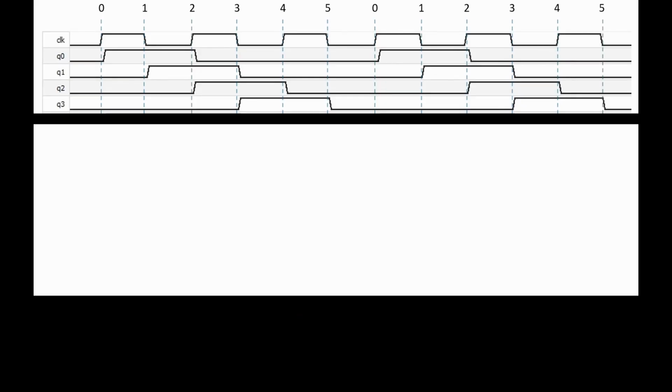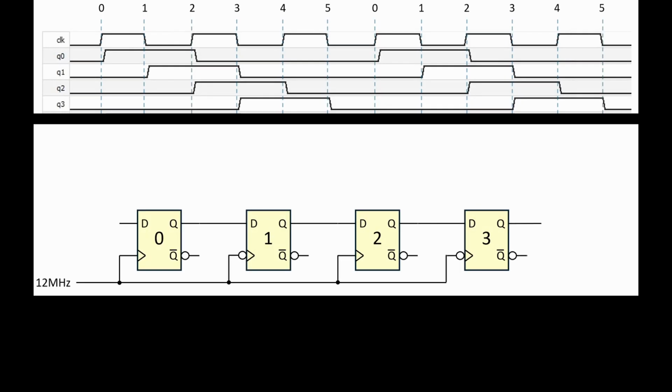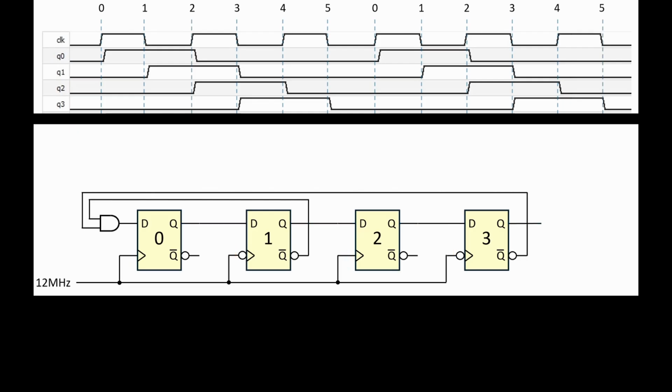We're going to use a 4-stage register chain where every other stage is clocked on the opposite edge of the oscillator. The relative stepping between each Q output is therefore 1/2 clock cycle, so the Q0 output propagates through to the Q3 output in 4 1/2 clock steps. The trick here is using the inverted Q1 and Q3 outputs to feed D0. The rule is that when latches 1 and 3 are off, D0 turns on.